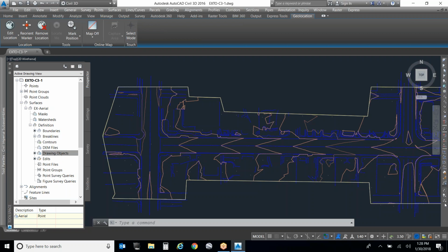Then you can actually explode those and export those to a separate file and just have it be a text annotation. That way you don't have to reference in the surface at all. You can just have, because that's ultimately what you're after, these labels that are not going to change because your surface isn't going to change. So you can just extract those labels. And so anything that you have in the surface that's displayed, you can extract.